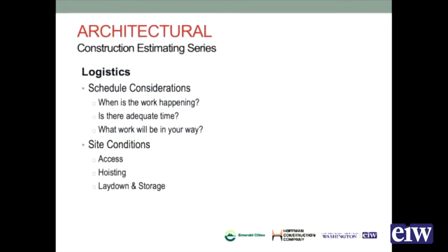And site conditions, so things like access. Do I have access to the work, or is the access such that my productivity is going to be impeded? And I'm going to need to estimate 4 hours to do the work where it should only take 2 hours.